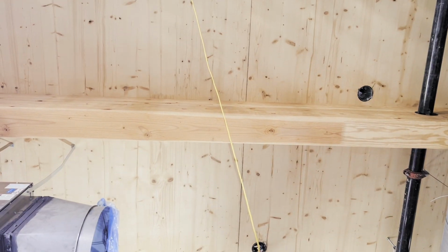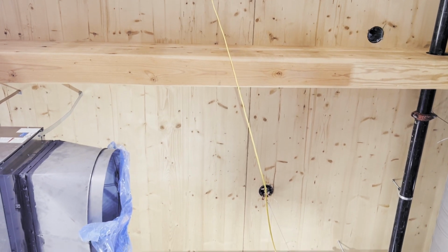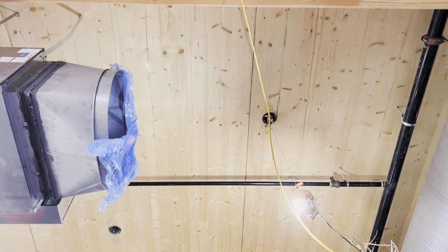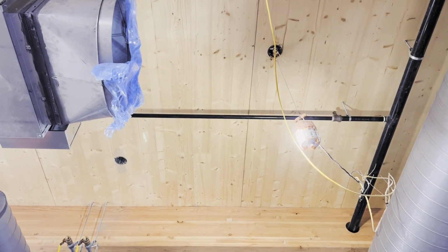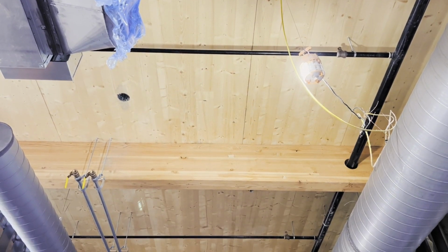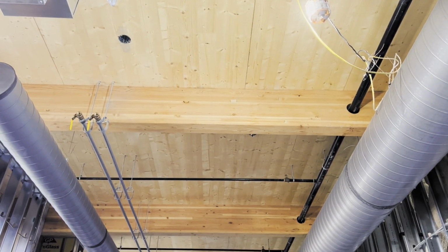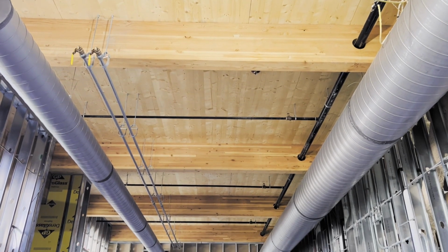So we can also look at the number of penetrations in terms of a per 1,000 square feet basis, again, to give us a metric. It's not to say that a certain number is the target goal, but it just allows you to evaluate several different designs to see, is one more efficient than another in terms of these number of penetrations through the timber members, and how can that impact the cost of the mass timber package.